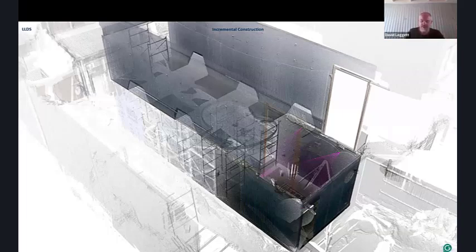Another aspect, just to throw this one in, is we had the ability, mainly because of our connection at the University of Melbourne, to actually do a point cloud scan of the space before the beams were installed. So here you're seeing that the concrete walls have already been cast, and we've got a point scanner, and we're locating exactly where those walls are, because although in our model it would be perfect for them to be like 4 meters or 3.9 meters apart,